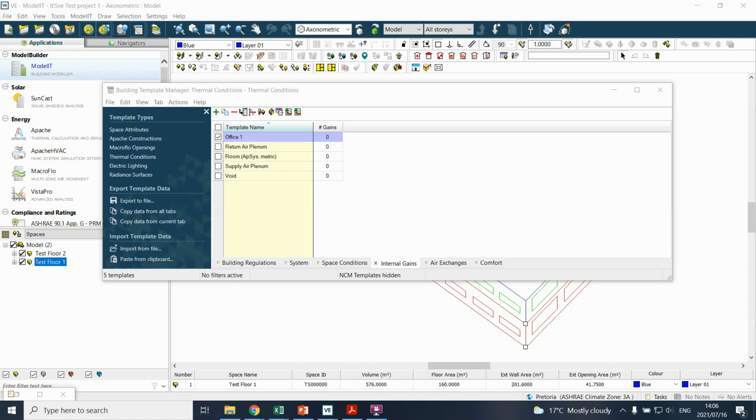Good. Welcome back. This is part of a series of videos on using the IESVE building performance tool, and we are busy unpacking the use of the Building Template Manager. Remember, the Building Template Manager is an important aspect of this whole analysis you'll be doing, because your geometry doesn't carry much information. The rest is really all integrated into the Building Template Manager and where that then gets applied to the spaces